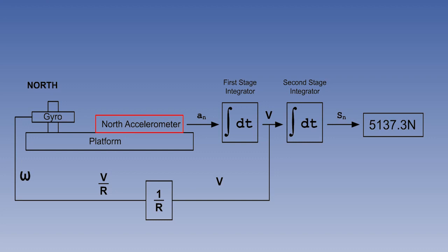Accelerometer bias is next. The accelerometers are designed to give 0 output for 0 input, if properly leveled. However, due to manufacturing imperfections, there may be some slight output when the accelerometer is perfectly stationary and level. This is called accelerometer bias.